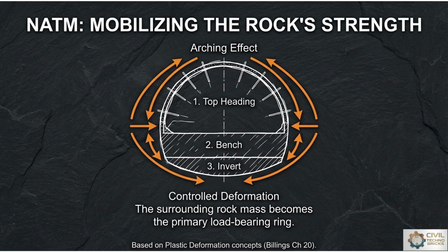Rock mass rating and the Q system are commonly used for tunnel rock classification. The rock classification is based on sedimentary rocks, metamorphic rocks, and igneous rocks on the basis of geological conditions. But we can prefer strong and intact rocks for tunneling, which give hard strata and hard support. Rock classification considers joint spacing, groundwater conditions, and discontinuity orientation. So proper rock mass evaluation improves tunnel stability analysis and support design.